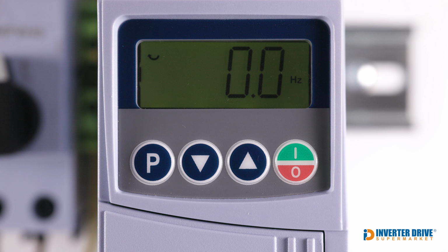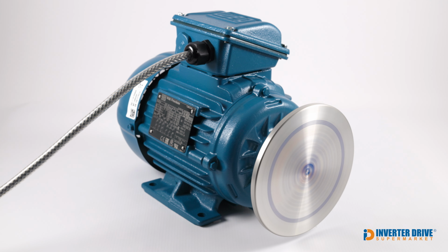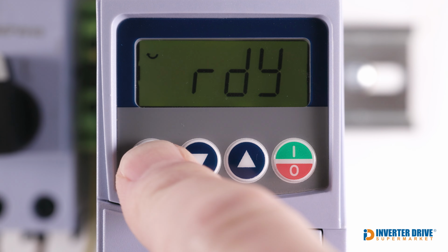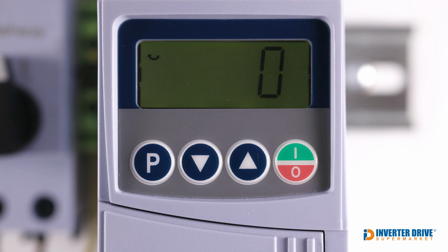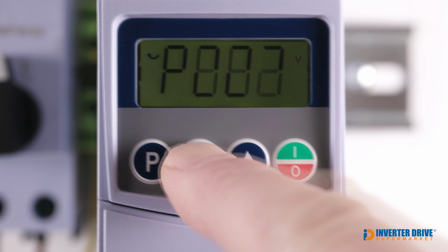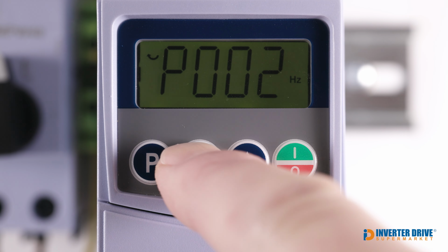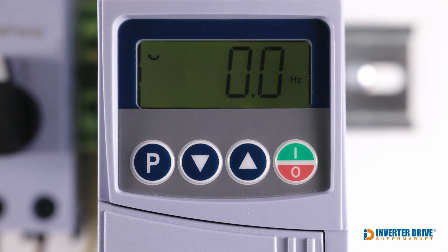Okay, let's start the motor and see how quickly it accelerates. It's now much quicker. The deceleration time is quicker too. In some applications, the deceleration ramp may not be required at all. For example, when the motor is connected to a low inertia, high friction load. So, parameter P229 can be set to 1 to change the stop mode to coast to stop. Just as it suggests, this causes the inverter to cut the output immediately so the motor will simply coast, eventually coming to a stop. Let's try it out.